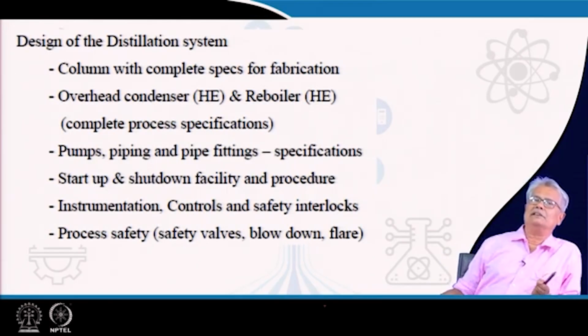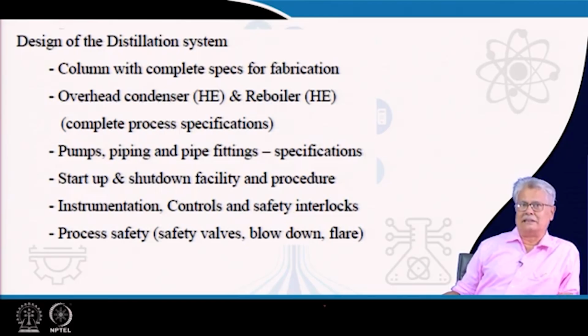That means, as a part of the design of distillation system, you are going to provide a column with a complete specification for fabrication. That is the drawing that I have mentioned. The details of the heat exchanger, which are the condenser and the reboiler, pumps, piping and pipe fittings, their specifications and sizing, startup and shutdown facility and procedure, definitely this has also to be defined.